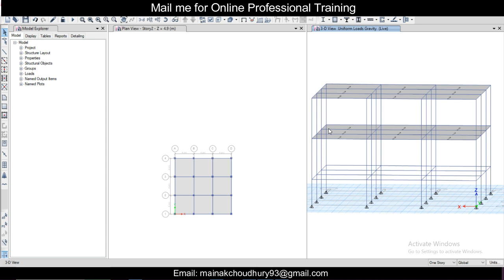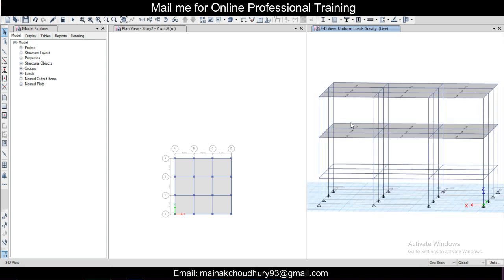Live load and dead load, floor finish, and shell load have been applied. Now we have to apply the floor load. You can calculate the floor load. We are adding a default floor load of 7 here, but you can calculate the wall load and add it, which I have shown in the previous videos. But let's add this here simply.